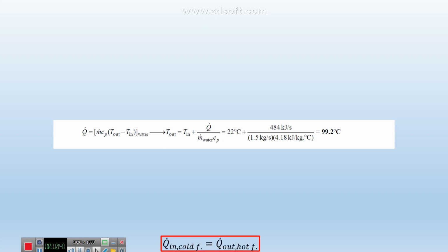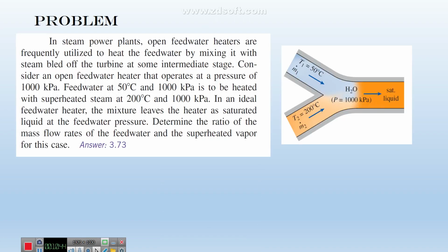Now let's solve another one. This question is for an actual mixing chamber. We have two streams. The first one is probably subcooled liquid. You have the temperature for the first one, and the second one, this stream, is superheated vapor. So here you have the temperature and pressure, so you can find the state of this water. This is probably subcooled, and then this is the superheated vapor.